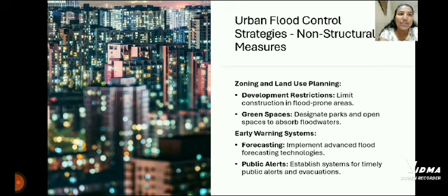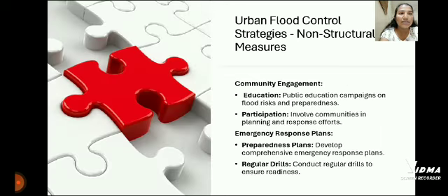Urban flood control strategies. Non-structural measures. Zoning and land use planning. Development restrictions. Limit construction in flood prone areas. Green spaces. Designate parks and open spaces to absorb flood water. Early warning systems. Forecasting. Implement advanced flood forecasting technologies. Public alert. Establish systems for timely public alerts and evacuations.